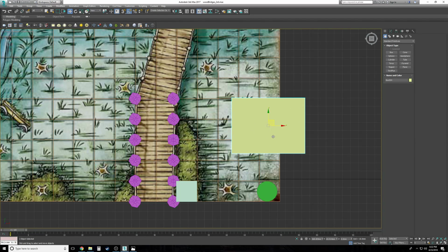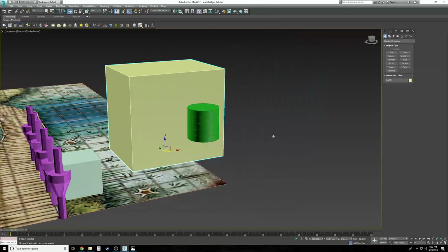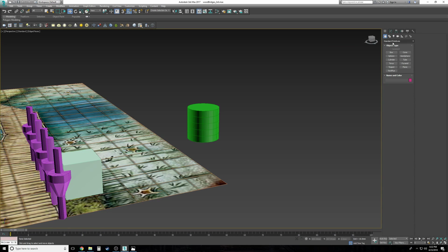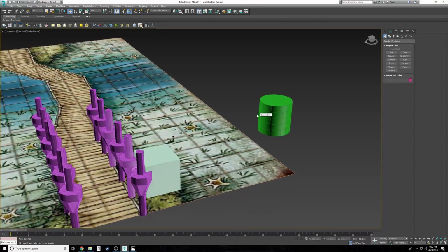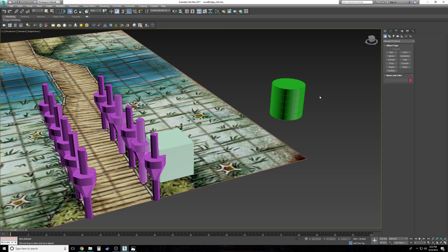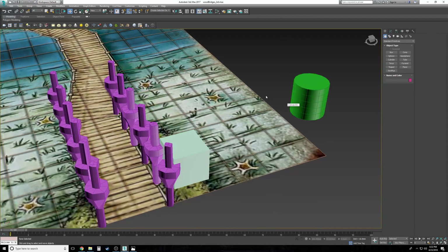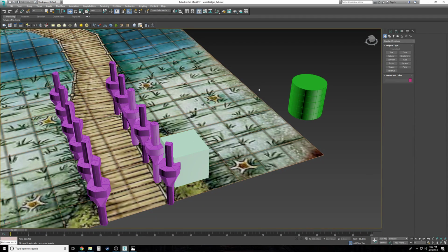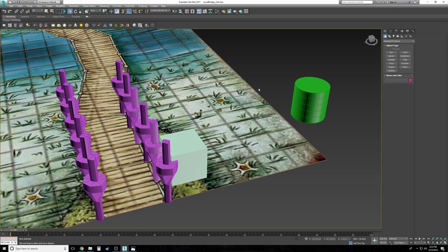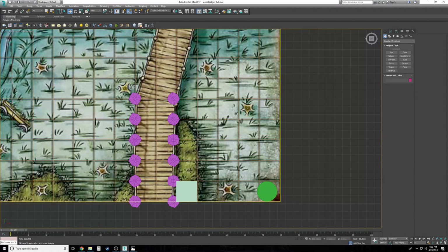Putting holes into geometric shapes like a cube means that you have to use the boolean tool, which is what we tried to use earlier. It's a tool that fuses two items together and also is a cutting tool. It's a complicated system. It doesn't really work every time. It's not as efficient, so it's better just to avoid it if you can.